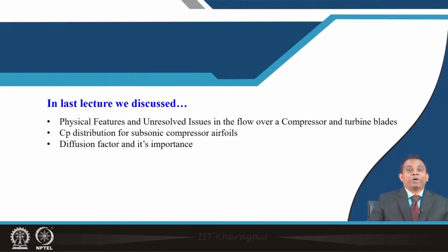We have discussed the high aspect ratio blade and the low aspect ratio blade, and we realized that by changing the number of blades, we are basically changing the diffusing passage between two blades. This passage is responsible for the rise of our pressure. So many times, in order to check the design, people consider the diffusion factor as one of the calculating parameters.